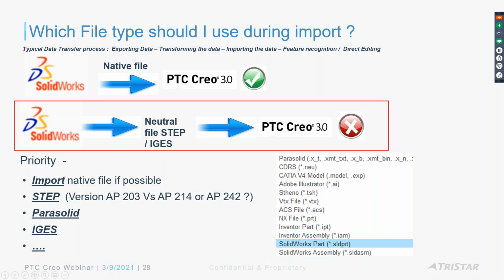Do you want to directly work on a SolidWorks file in Creo, or would you rather have them do a first conversion, exporting it and then you importing it here? What's really happening is that data gets exchanged 2 times, and it's obvious that it's going to lose some geometry, depending on how complex the geometry is. So we want to avoid that. I'm not saying that native file import is going to be perfect, but you may have to test it out. It depends on the geometry.